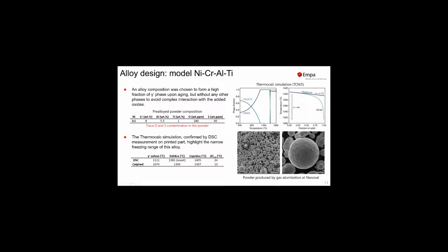Here are some Thermo-Calc simulations where you see that the gamma prime phase is stable. We also did some solidification simulations, equilibrium and Scheil, and we confirmed this later on the alloy. So we have a fairly narrow freezing range compared to other nickel-based superalloys.